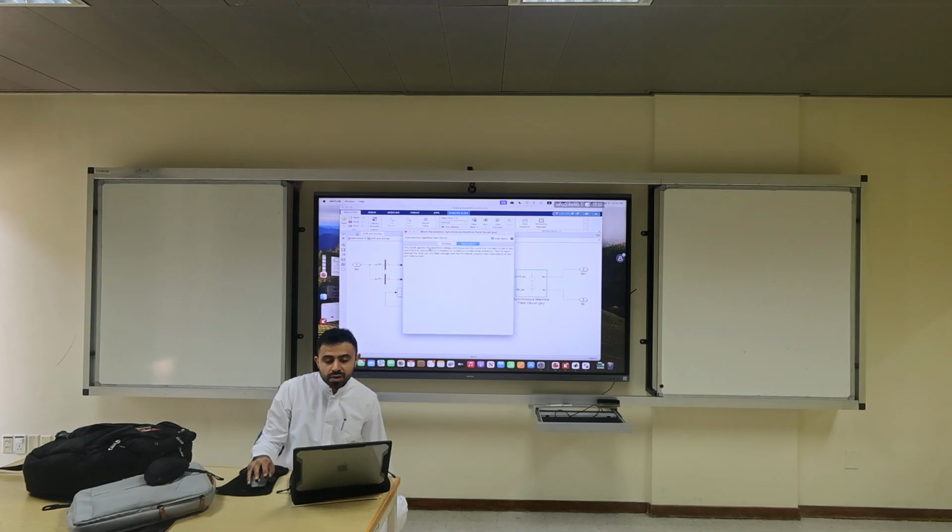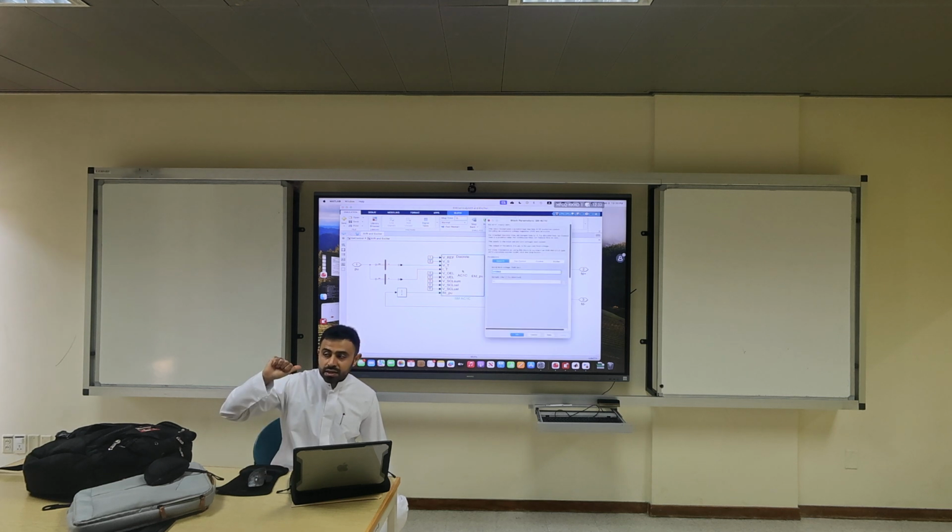So this is the synchronous machine field circuit. This one, the field circuit, is connected to it. This is for electrical reference. This is the one that gives you IF. What's the output? IF. You put EF. What's the output? IF. And then you have positive DC, negative DC. You feed these two terminals where? To the machine, positive FD. So this is the AVR and exciter together. Inside this model, it takes care of the exciter as well as the AVR.